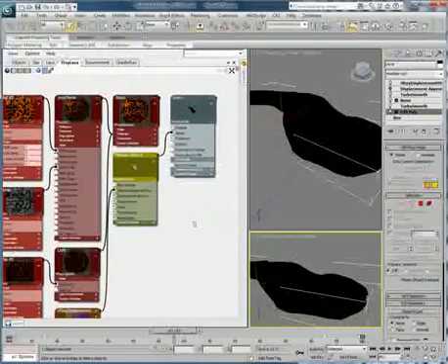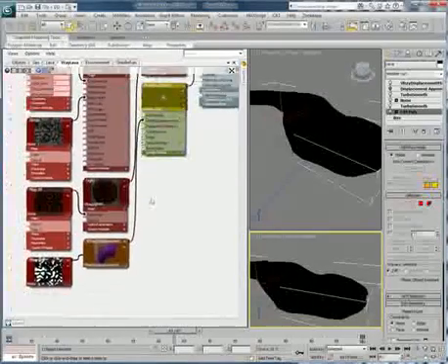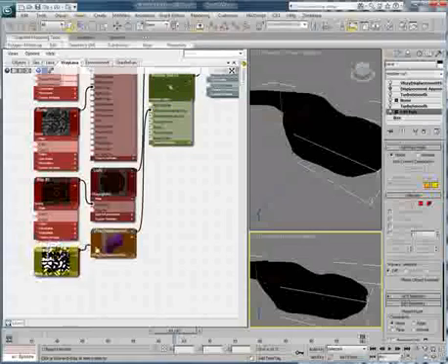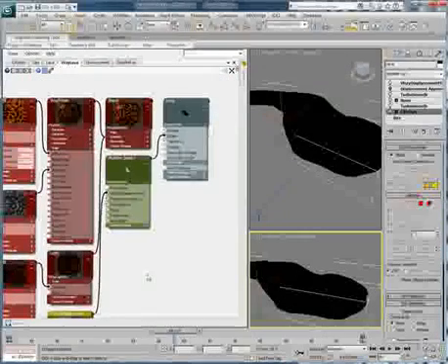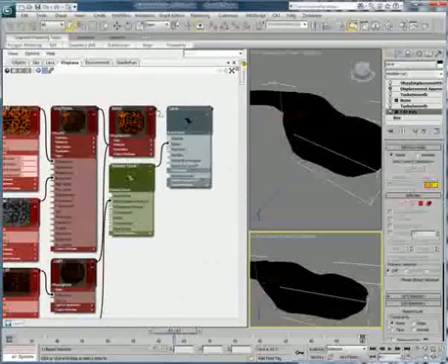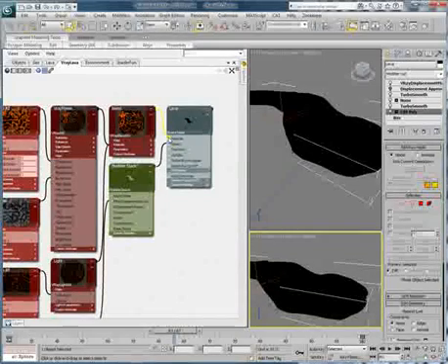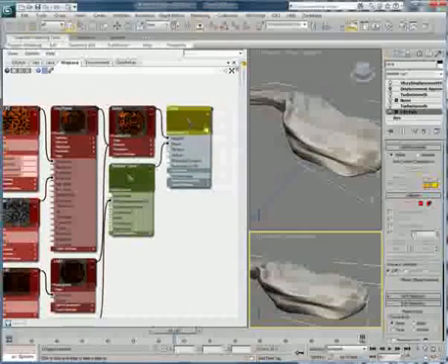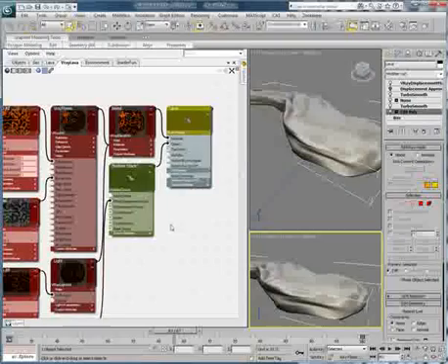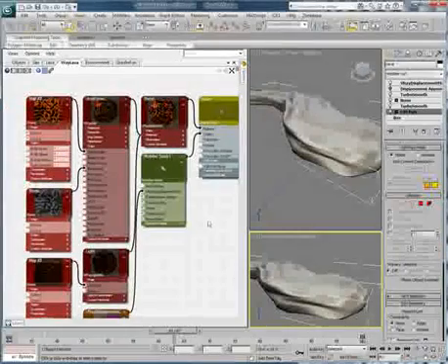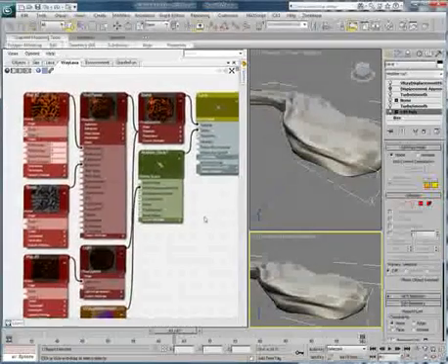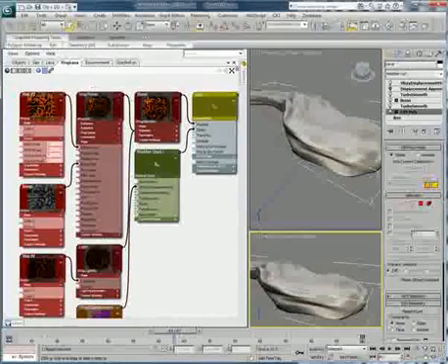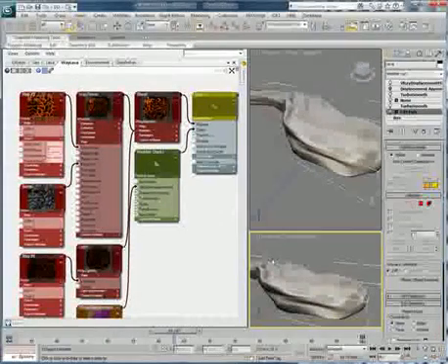I'm just going to turn on the V-Ray displace. And here's the V-Ray displace and the texture that it's using to displace in our V-Ray displacement node. So we're working in a little bit of the object in here too, and I'm just going to pipe this material into that lava object, so now we're using this V-Ray material. So you can see that with third-party renderers such as V-Ray, Mental Ray, other renderers you might be using.